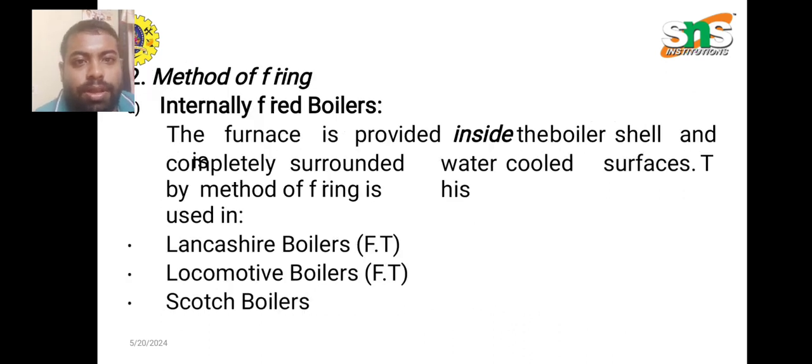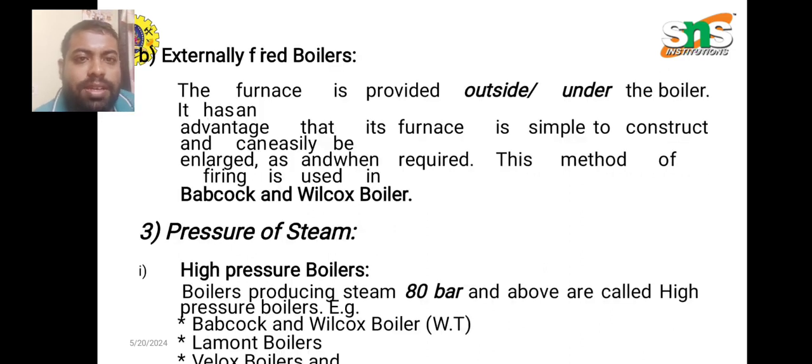Method of firing. Internally fired boilers: the furnace is provided inside the boiler shell and it is completely surrounded by water cooled surfaces. This method of firing is used in Lancashire boilers, locomotive boilers and Scotch boilers. Externally fired boilers: the furnace is provided outside or under the boiler. It has an advantage that its furnace is simple to construct and it can easily be enlarged as and when required. This method of firing is used in Babcock and Wilcox boiler.